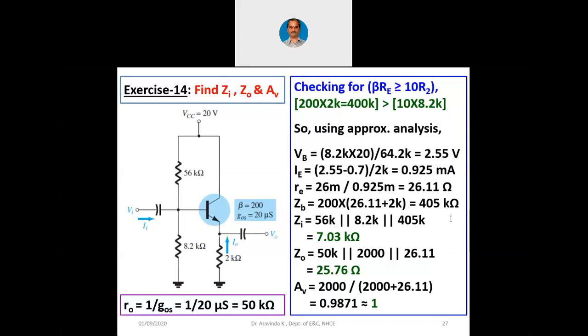And so, small re is internal to the BJT. I have told you this how many times. Don't keep on asking the same questions again and again. The small re, whenever we are using it, is always internal. I had told this nearly 10 times till now. Whenever we use capital R, that is a DC quantity, a physical resistance. Whenever we use a small r, that is dynamic resistance. That is why this R naught also is internal to the transistor itself, because external resistors are used for biasing the circuit.